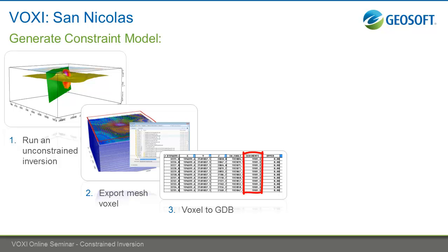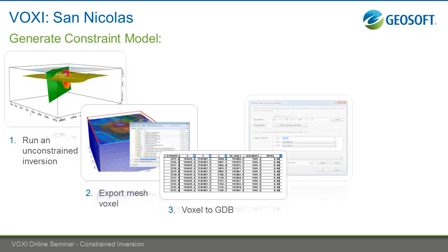So having the grid here, sampling it to the database, I can see that my sediment layer in this part of the model, at these XY locations, is actually down at 101.3 meters. So this is the value of this surface across the model here. Now I can do some channel math on those channels, and then I can use that to generate an upper bound.